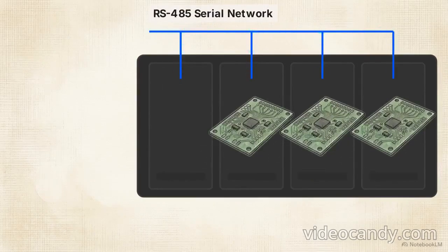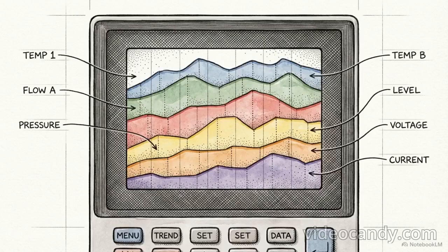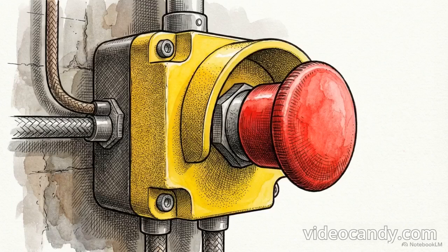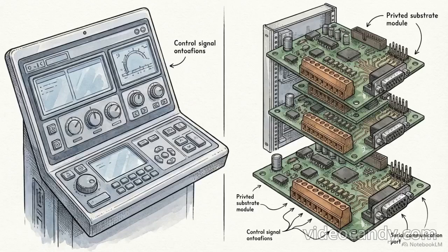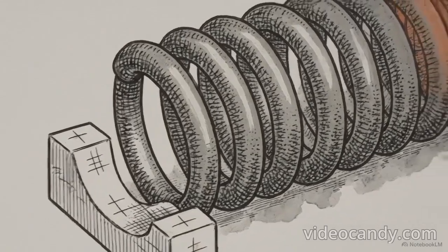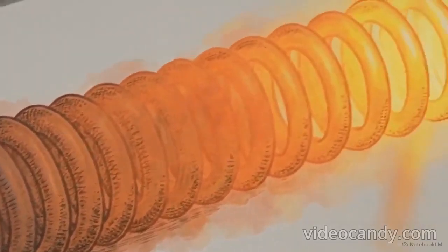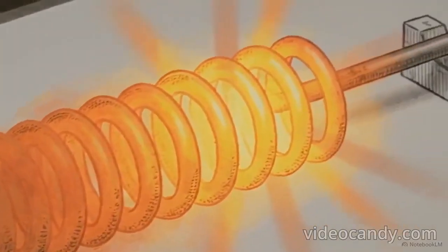Watch how this panel controller strips away its interface to become a bare substrate-type printed circuit board. Eliminating front panel screens saves space. These faceless logic nodes mount directly into the chassis, communicating with central PLCs via high-speed RS-485 serial networks. Engineers also attach passive devices to these exact same networks. Digital indicators and recorders monitor the data flow strictly to log historical process values and trigger hard safety shutoffs, executing safety logic without actively driving the PID loop. Whether housed in an expensive digital touchscreen or a bare green circuit board, the internal PID mathematics remain identical. The topography changes solely to navigate the physical constraints of the hardware environment.